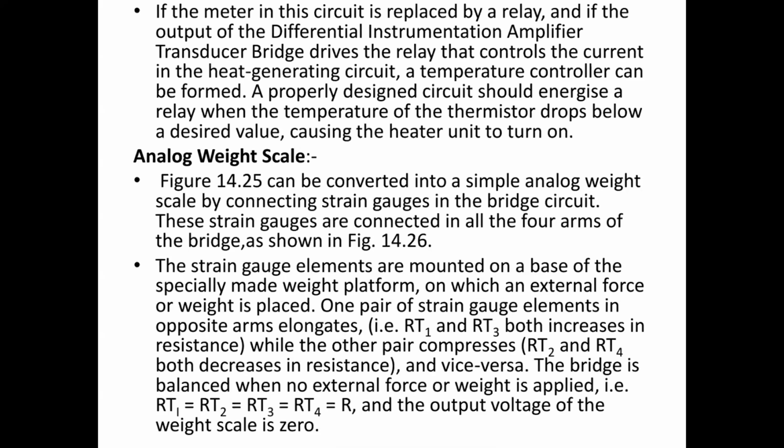That is the same circuit. If you use resistive transducers, it is going to measure the physical quantity. If the physical quantity changes, the bridge becomes unbalanced, which you measure through the meter. If you replace the resistance transducer with a thermistor, then when there is a change in temperature, the resistance changes, and accordingly the meter will indicate the temperature change. If that meter itself is replaced with a relay, it becomes a temperature controller.